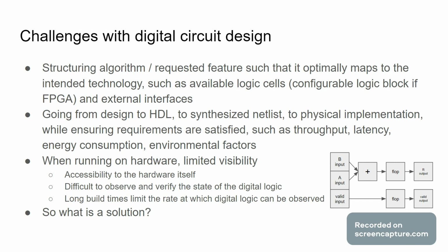This process is pretty lengthy, even for simple designs, and especially when you're trying to maximize the resource utilization on your part. You're trying to fit as many features as you can so you can maximize whatever requirement like throughput or minimize latency, or just try to get as many operations in as possible. When you get closer and closer to the boundaries of the chip, it becomes harder and harder to get through the whole build process. So that's pretty time consuming.